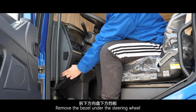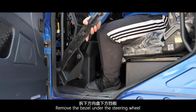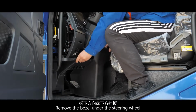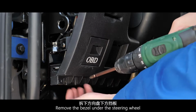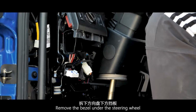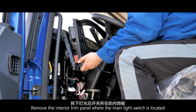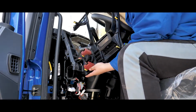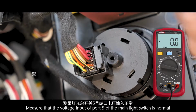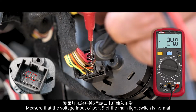Remove the bezel under the steering wheel. Remove the interior trim panel where the main light switch is located. This is the main light switch. Turn the multimeter to the appropriate voltage. Measure that the voltage input of port 5 of the main light switch is normal.